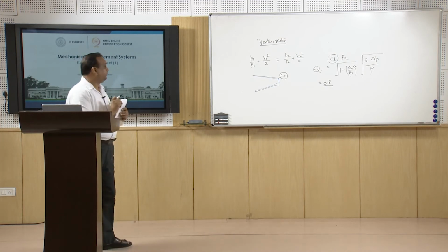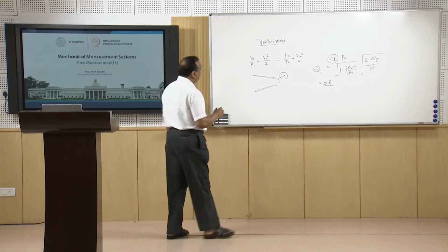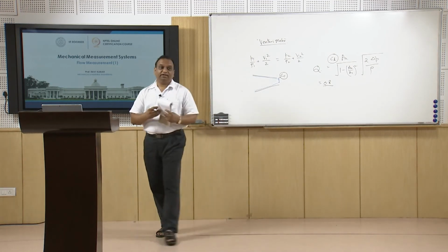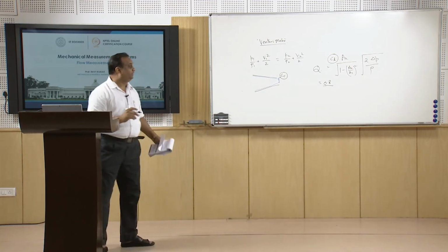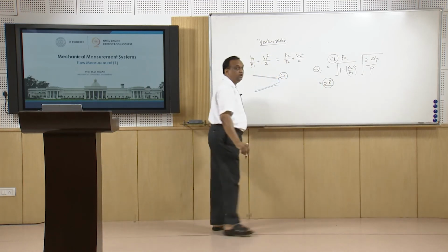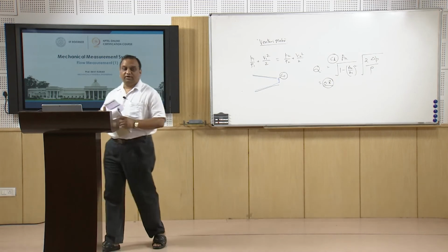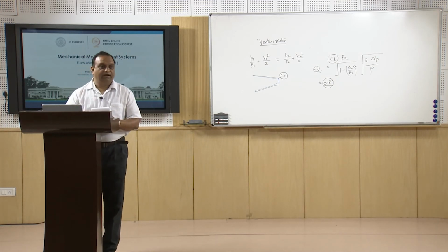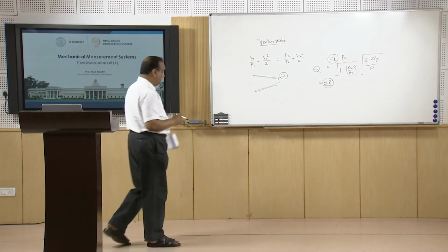So the benefit of this type of obstruction type instrument is high recovery. I mean the pressure recovery is high, because CD is, let us say, 0.8. If you compare the CD of an orifice meter, I will discuss the orifice meter also, it is quite high. It has well established characteristics.